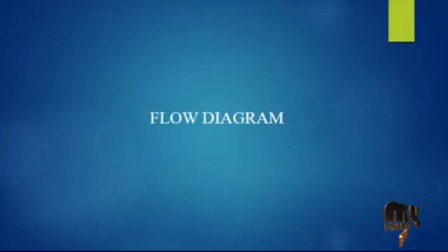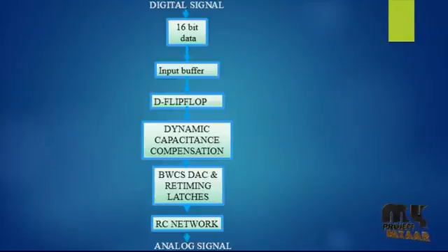Next we see about the flow diagram of our product. In this product we use current steering digital to analog converters, which perform an important role in communication and video systems. Current steering digital to analog converters have the advantages of speed, linearity and power efficiency. There are three different architectures to implement the switched current source: array, binary and unary segmented, and they account for power consumption, chip size and circuit complexity.